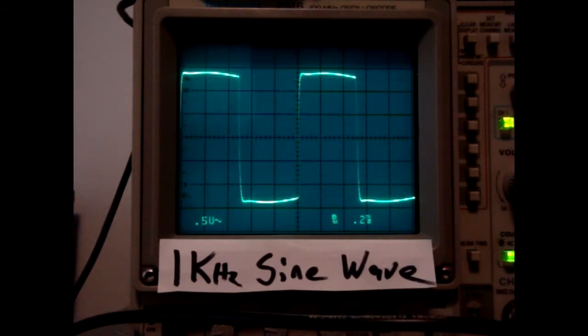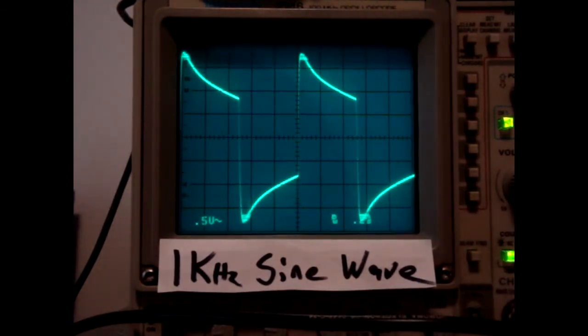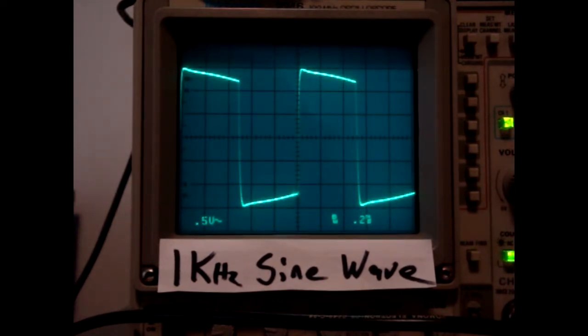And how we'll see that is, here at the very leading edge, we call it the tip of the square wave, if we have an exaggerated treble response, this will spike up and not look even. See if I can simulate it here with the EQ. There we go. See, as it starts going up, I just turn the treble control. I have these adjusted to be square.